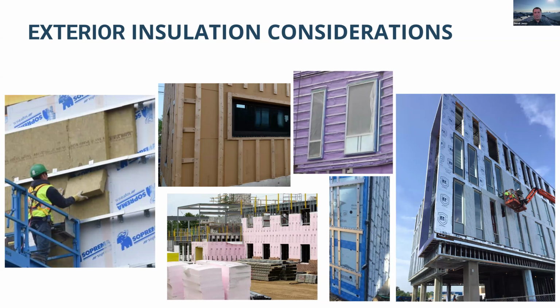So one thing to be careful about if you're in certain climate zones, colder climates especially, is what type of exterior insulation you're putting on the building. Here we've got mineral fiber in between these vertical rails, with what looks like fiberglass clips supporting those rails. This is a rigid foam, a polyiso with a foil facing.